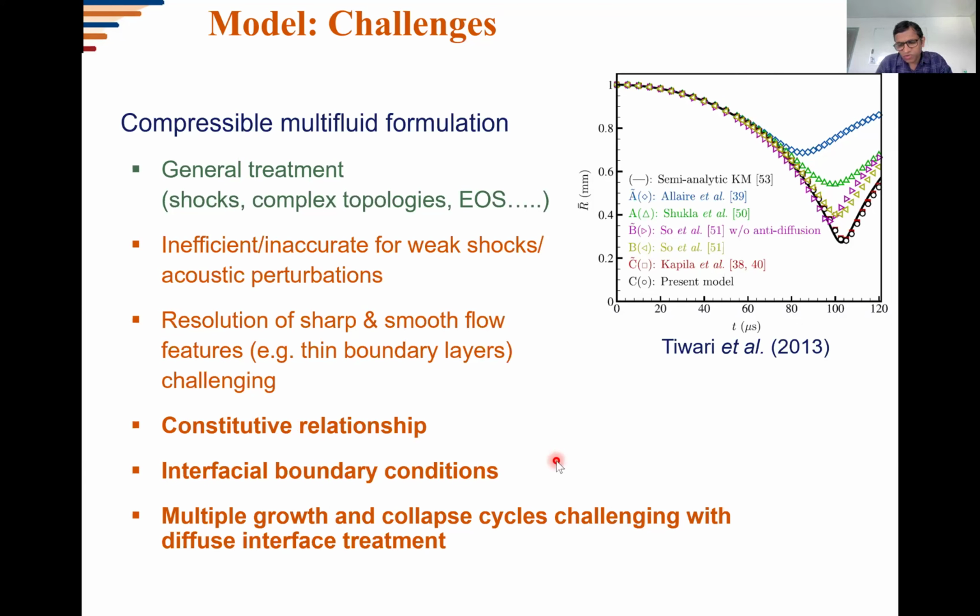So here, when we look at microcavitation events, which are what should be the primary focus when one looks at these biomedical applications, then it's not really the accurate wave transmission or shock wave transmission that governs the dynamics of the bubble, but it's more to do with Rayleigh-Taylor-like instabilities which set in when a bubble accelerates, basically, when the interface of the bubble accelerates.